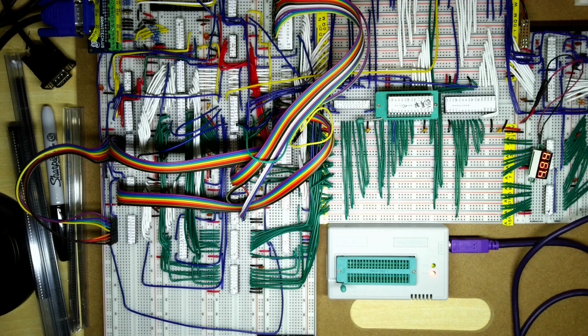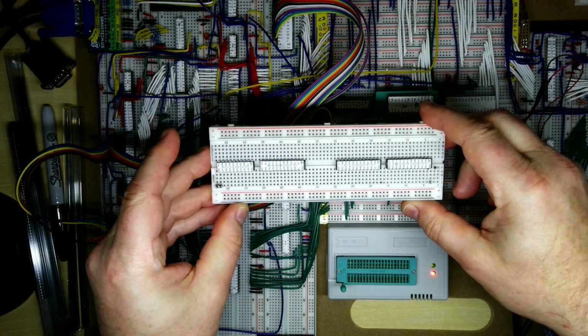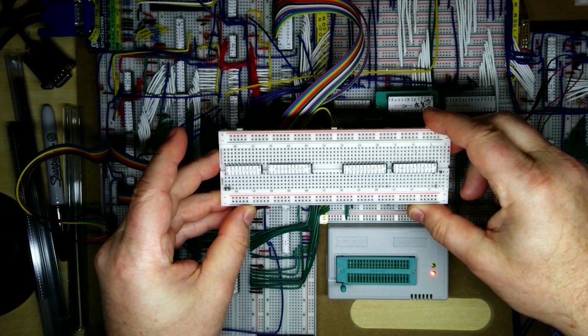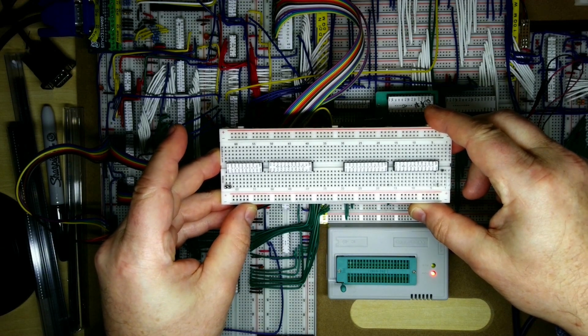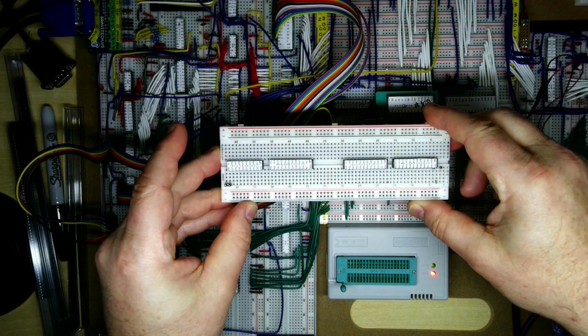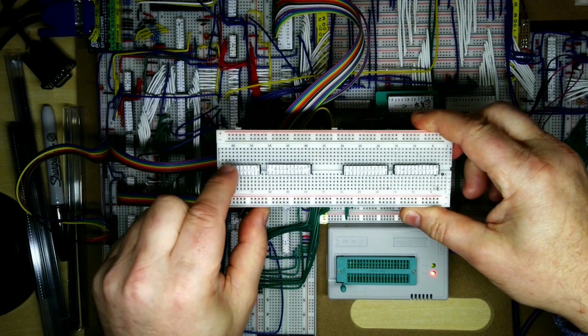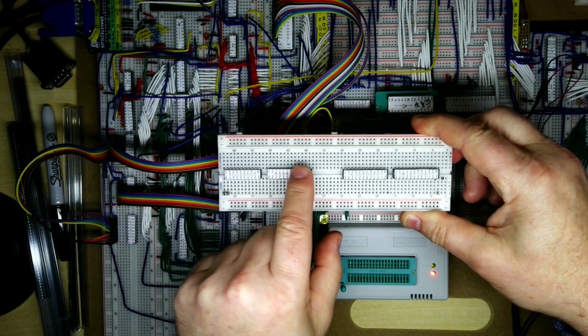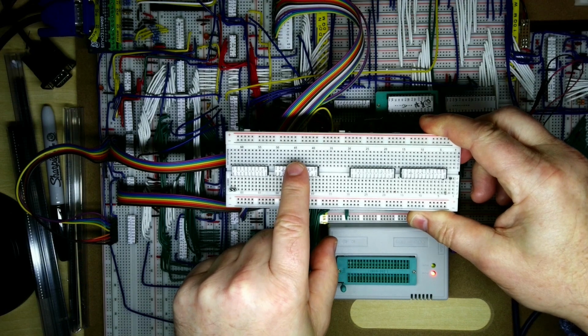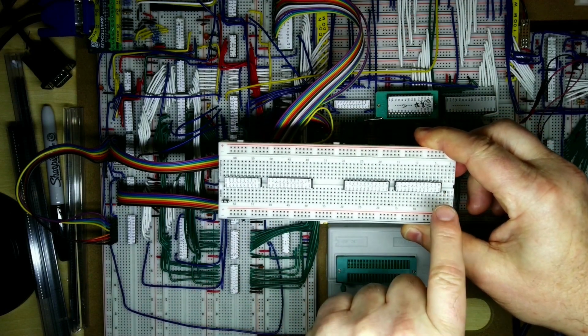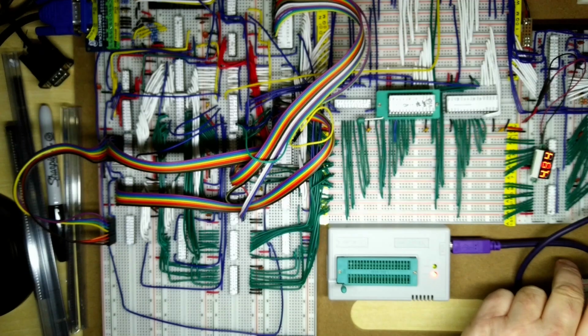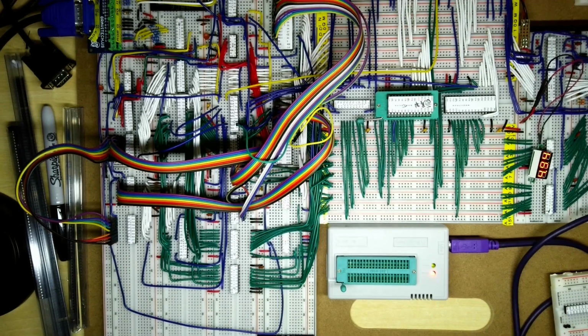Okay, so I've finished programming and testing all 4 PLDs, and I've just put them in a breadboard here with the labels on just so that I don't damage them before I put them in the board. So what I'm just going to look at now is where these are going to go. So we've got our CPU1 and CPU2, which is the 24 pin version, and then we've got the CRTC1 and the CRTC2 versions. Now where these are going to go are on the board over here.